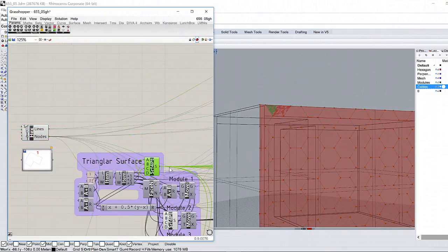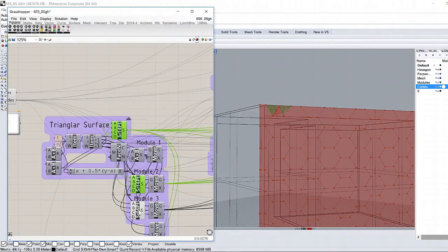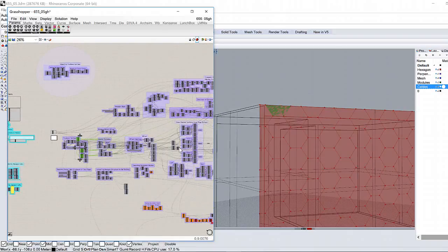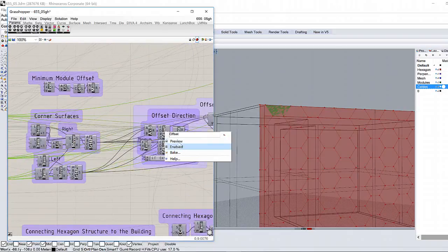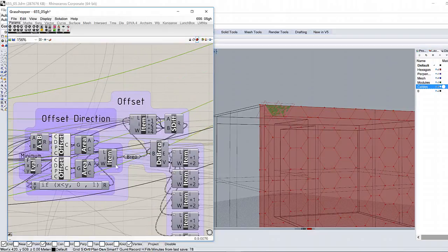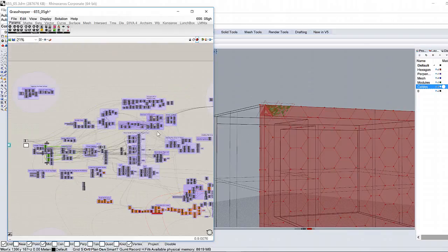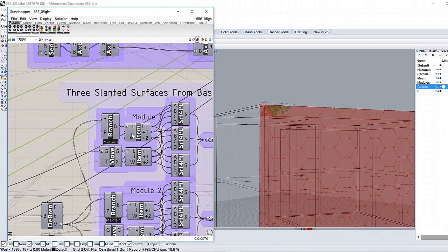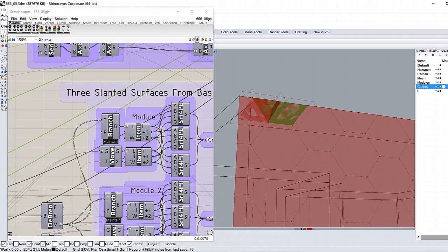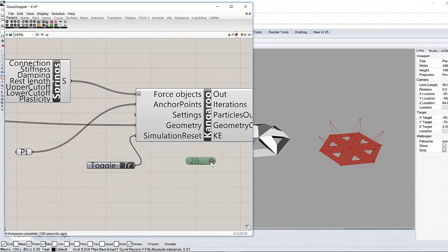The approach that I've been using in this project is using these three triangles and then getting two different offsets, because while flexing the model the order of the points will change, but we need the smaller one for this solid difference. Then this solid difference is protruded to create a shape like this. We can also use other methods like Kangaroo to get similar results.